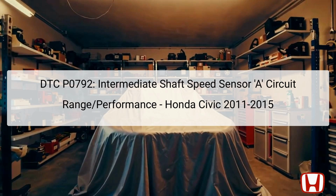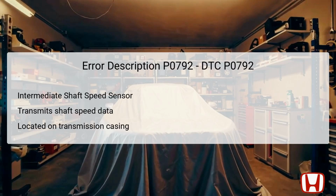Electrical issues can manifest due to various reasons, and they are often detected through the vehicle's onboard diagnostic system, which produces DTCs that guide technicians during troubleshooting. The error description for DTC P0792 highlights the role and importance of the intermediate shaft speed sensor. This sensor is pivotal in transmitting speed data from the intermediate shaft to the powertrain control module, PCM, which uses this information to manage transmission functions efficiently.